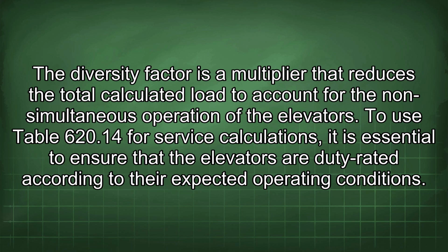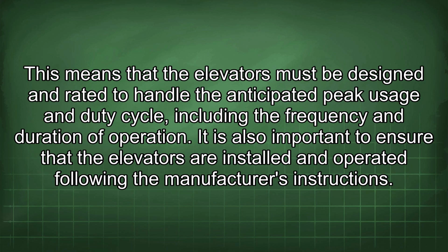The diversity factor is a multiplier that reduces the total calculated load to account for the non-simultaneous operation of the elevators. To use Table 620.14 for service calculations, it is essential to ensure that the elevators are duty rated according to their expected operating conditions. This means that the elevators must be designed and rated to handle the anticipated peak usage and duty cycle, including the frequency and duration of operation.